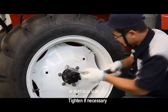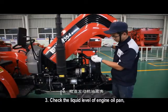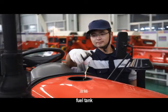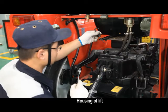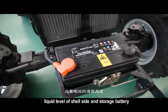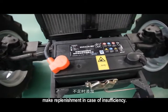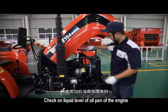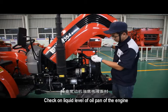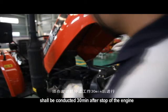Tighten if necessary. 3. Check the liquid level of the engine oil pan, water tank, fuel tank, housing of lift, liquid level of shell side and storage battery. Make replenishment in case of insufficiency. Check on liquid level of oil pan of the engine shall be conducted 30 minutes after stop of the engine.